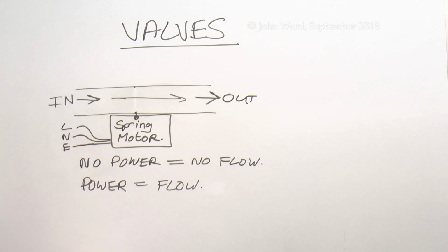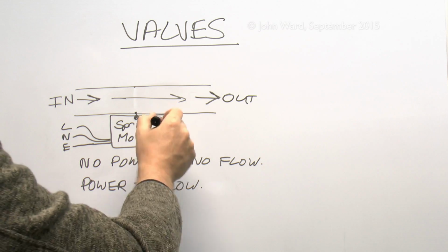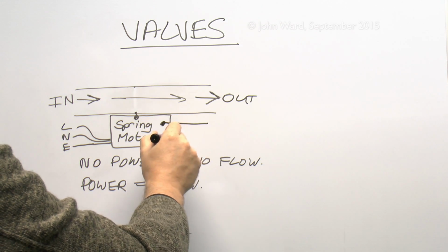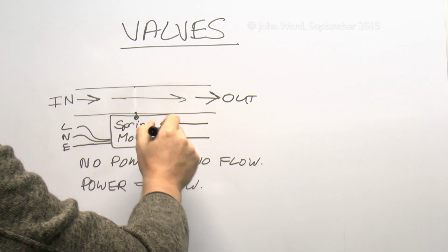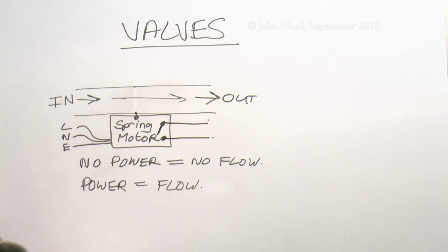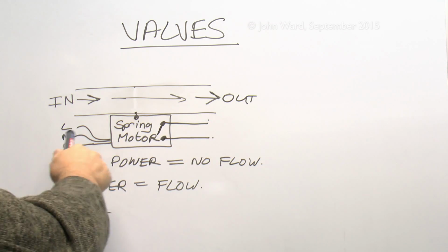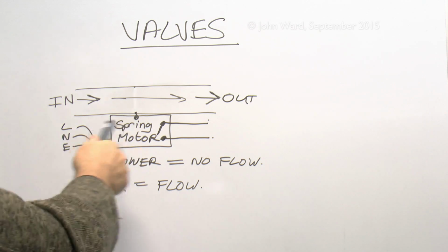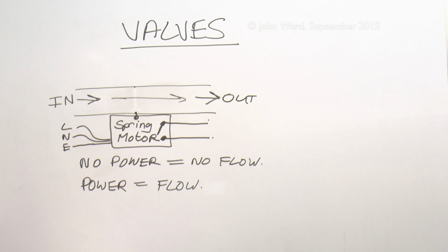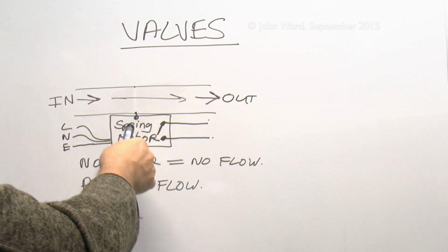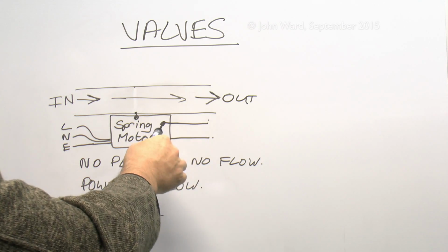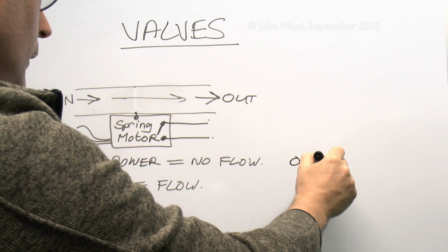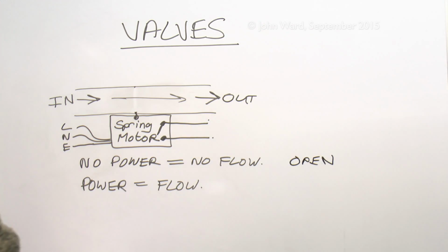Now for heating systems there's normally an additional component inside, which is a switch. And just like thermostats, that's just an on and off device, and that's generally brought out on two additional wires outside, so it's fairly common you get a 5-core wire attached to these, and most valves are actually supplied with a length of 5-core flex already attached. And when there's no power and the valve is essentially closed, then the switch is open, so we'll put open. So these two things are not connected.